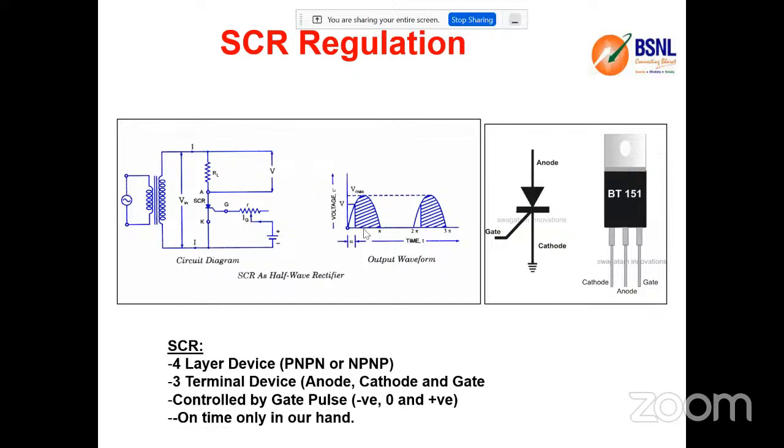So like that, the duty cycle is decided by the on time or off time, that is, at which time you are going to switch on or off. In a very simple example, take 100%; if I have 80% on time, my output will be 80%. If my on time is only 10%, my output will be only 10%.